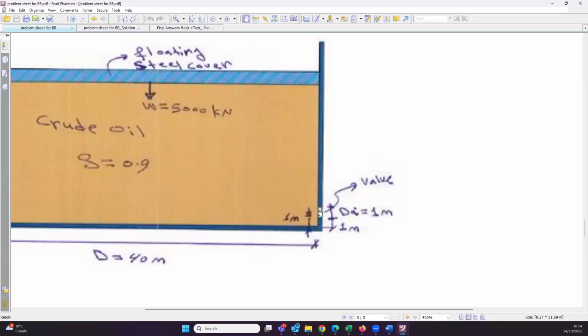So that's why we give some space at the bottom for safety reasons, because this will be at the floor, or on the ground, or even on a tanker, wherever. So this side is safer. And as you can see, it's almost 1 meter from the bottom, so that it doesn't get hit and break, because if it breaks, the oil will leak as well. So that is a practical reason for putting the valve on this side. But if you have a valve at the bottom, then you just do the calculation without adding this 1.5, and the height will automatically adjust because the valve is at the bottom.